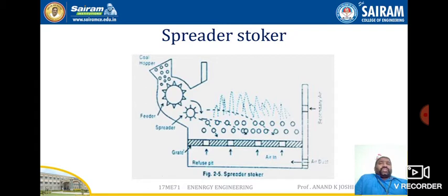its periphery. Other types of feeders such as oscillating drums, endless belts and spiral screws can be used. The feeder continuously supplies the coal to the spreader, a fast moving drum with blades, which in turn distributes the coal on the grate, as shown in the figure. So the fuel feed rate and supply to the boiler can be controlled by controlling the feed to the hopper and by controlling the spreader speed.